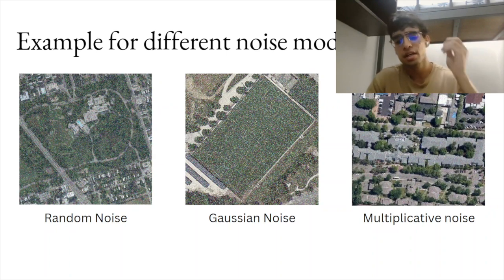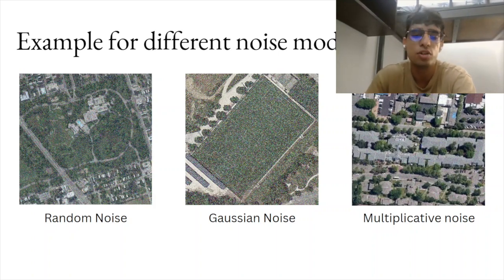The random noise is unpredictable variations in pixel values, often caused by electronic interference or sensor imperfections. It does not follow a specific pattern and can affect any part of an image, leading to a grainy appearance and degradation in image quality. The Gaussian noise follows a normal distribution with most pixel errors centered around the mean. It is commonly caused by poor illumination or high temperature in image sensors. The noise adds to every pixel independently, resulting in a soft, grainy texture.